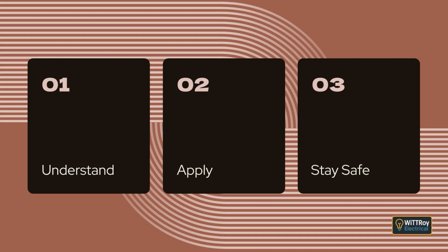Single-core cables enclosed in copper, aluminium, or other non-ferrous sheathing may be used only where the installation avoids the creation of excessive heating. Trefoil formation may be used, where the cables are run together in groups of 3 for their full length. Where trefoil is not used, cables must be installed as close as possible to each other. The sheathing must be bonded at both ends and at intervals not exceeding 30 meters to ensure equal conductivity and to control induced currents. Clause 3.9.11 Electromagnetic interference.